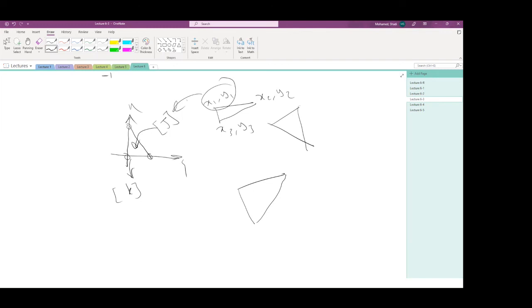In order to find the stiffness matrix, you need to find the Jacobian matrix. And in 2D, you can already start to see these changes once we increase the order from 2-noded to 3-noded. But once we move into 2 dimensions, this matrix is going to become a real matrix. It's not going to be a scalar. So it's going to be a 2x2 matrix. And if we move into 3 coordinates, it's going to be a 3x3 matrix.